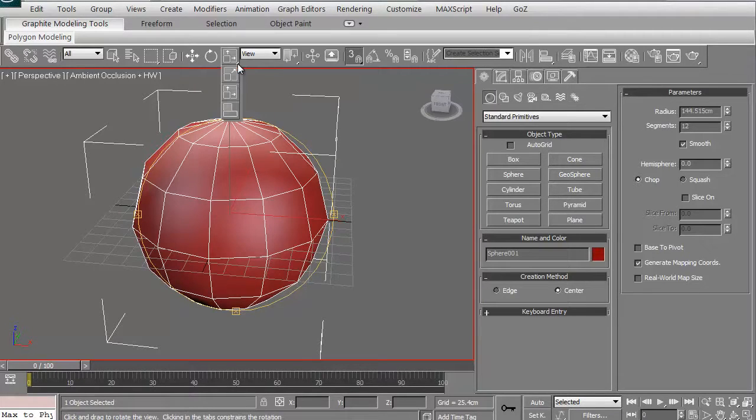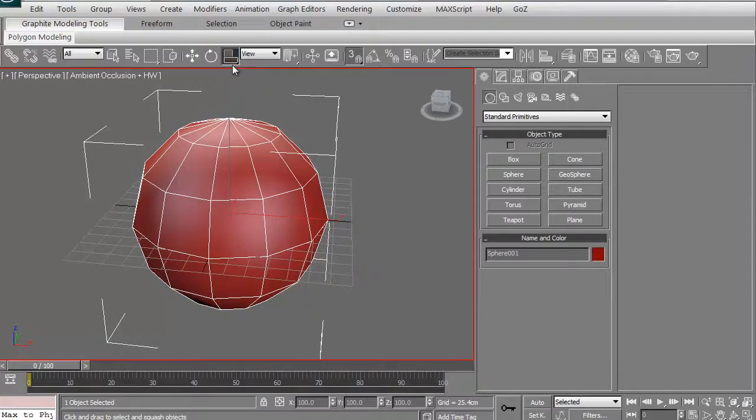So you can just left click and hold, and I can do a uniform scale, non-uniform scale, and then the scale from... it's a select and squash kind of scale. I'm just going to click that back and go back to my uniform scale. That's the uniform scale. This is the pivots. This is the center points.